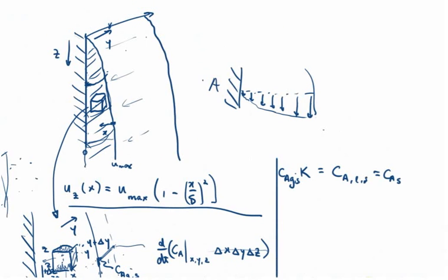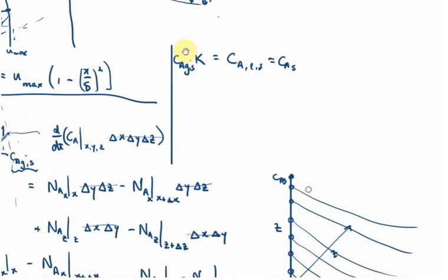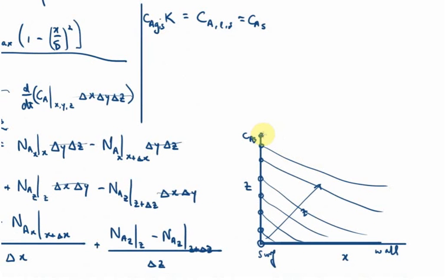So at x equals 0, it's fixed at that surface concentration. Because of equilibrium between the gas here and the liquid there, there will always exist some surface concentration in the liquid. So if you imagine right on the inside of this film, there is some concentration which is a discontinuous value. There's a value here, and then there's a different value immediately next to that. So it is a discontinuity. We are always fixed to this concentration CAS for x equals 0.